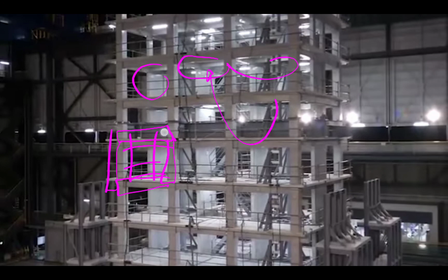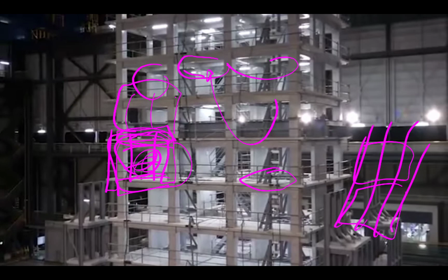It'd be very nice to have this like that, and then a two-way slab on this side, making them independent. That would be nice. You know, that means this could fail here. Some torque rotation would be created on that if it did happen to fail. But it makes independent zones. Now, if they just did that and did this, and then they just ran reinforcement all the way across, they're not independent anymore. Sag on this side, pulls on this side.